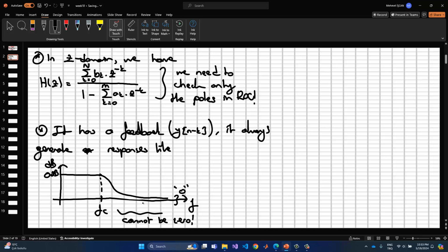Just remember the discrete low pass filter design. If we apply any signal that's higher than the cutoff frequency, for example a 500 hertz sinusoidal signal, then we will obtain some output for a given signal. For example, if the input signal has an amplitude of 1 at 500 hertz, then we will have 0.1.